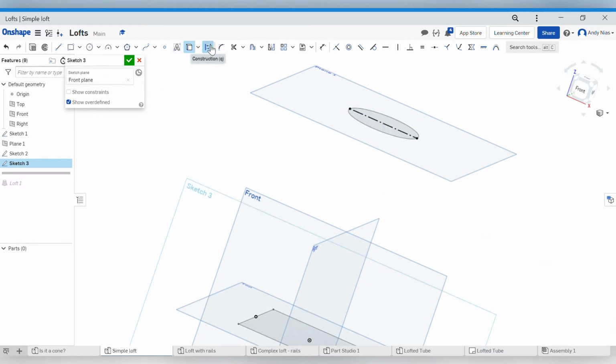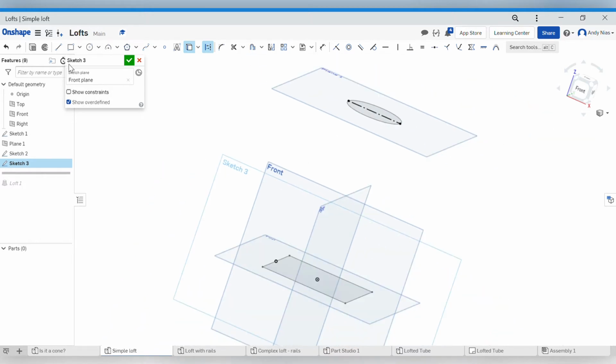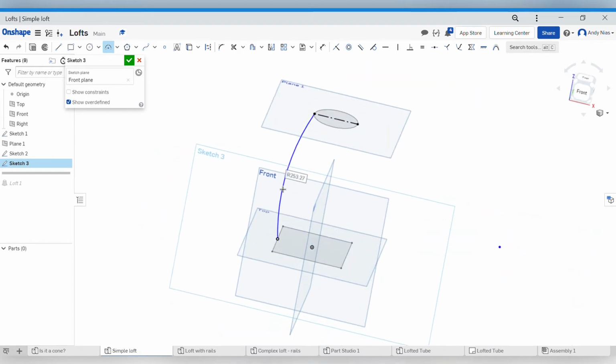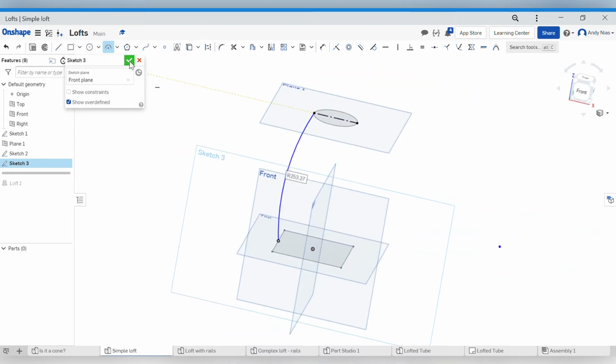Notice I hit the construction line. That means I've got the point, so I can connect my sketch, but the loft is not going to see that construction line. So there's my start and end point. If I go and get my 3-point arc, I'm just going to put a little curve between these two points, and come out a little way, maybe something like that. If you were doing this to a drawing, you'd have a dimension, but we're just playing, so that looks about right.